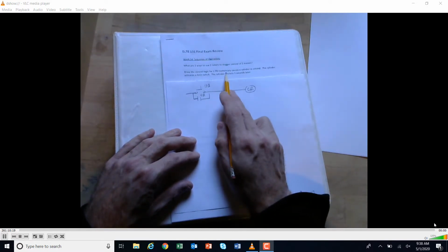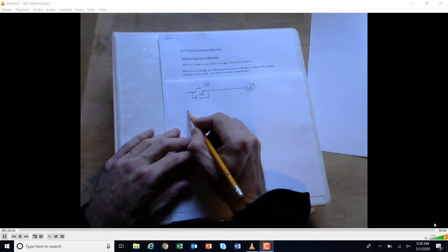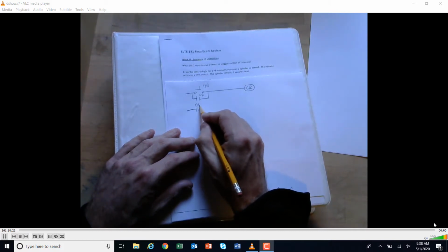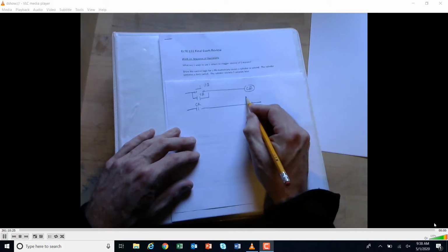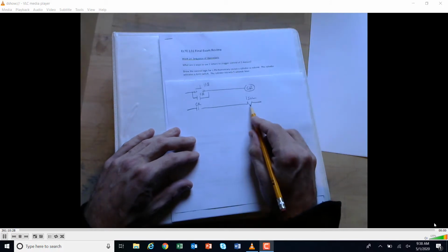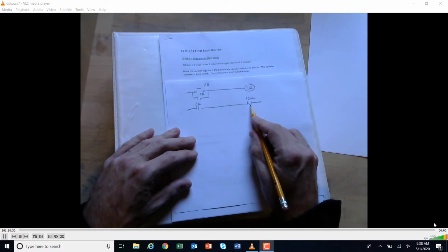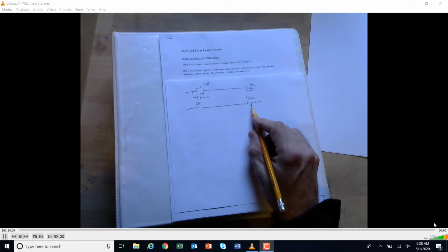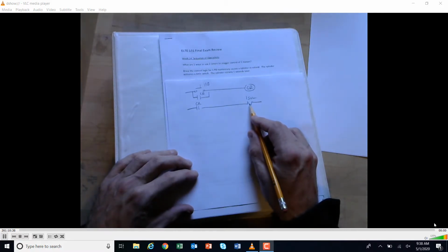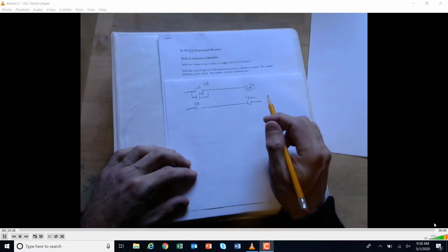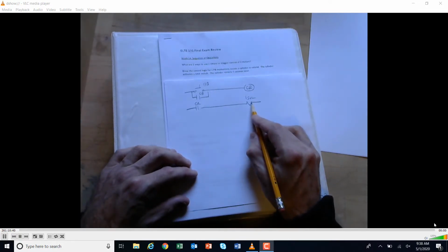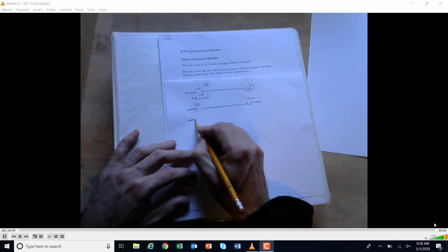And now it says it causes the cylinder to extend. So let's use that control relay to turn on a solenoid. And that is the solenoid. Let's just say it's a 5-2 single coil. So then it's going to extend. Cylinder is going to extend. The cylinder extends, and apparently it's going to hit a limit switch to indicate that it's extended. And so that limit switch